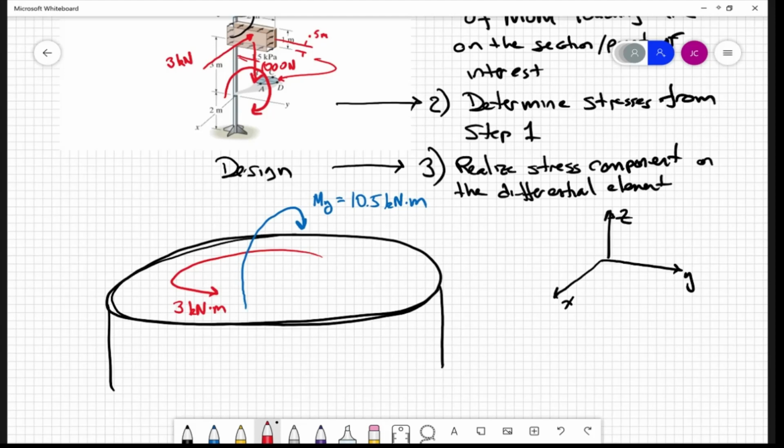A normal stress. What's that? A normal stress. Right, a compressive P on A stress. Does that make sense? Right, an axial stress, right? Because that would put a uniform pressure over area on that. Again, you could think about relocating that to the center line, and then that would produce the moment as well as that force, right? But the problem didn't ask that, so let's not carry forward on that. But if they did, that's what you would need, right?